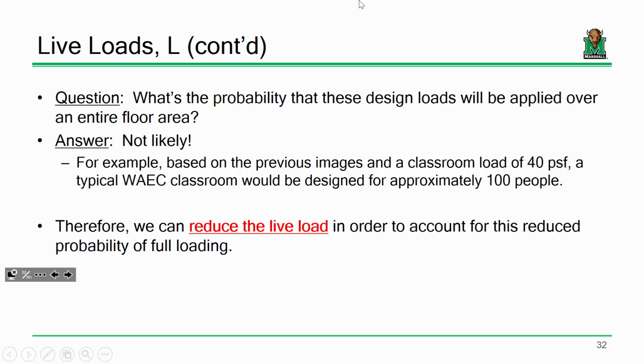So let me ask you a question. What's the probability that a room in this building is going to have 100 people in it 24 hours a day, 7 days a week? Well, that's a good point. You're exactly right. But in general, I'm talking more about from a loading aspect. Let me ask this question in another fashion. I mean, you're making a good point about fire codes, but let me ask you this question. What do you think is the probability that the floors will really experience those loads 24 hours a day, 7 days a week? Not likely.